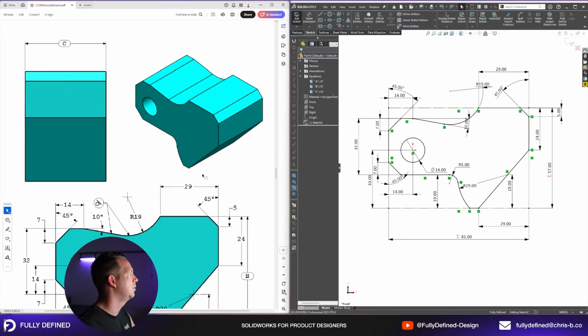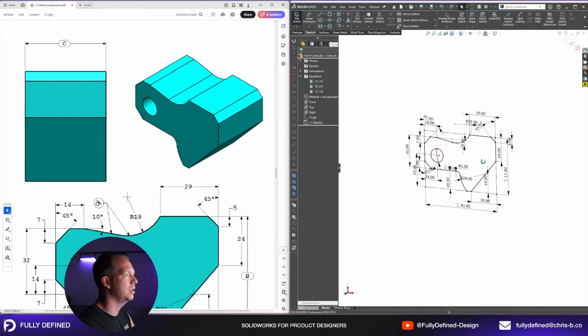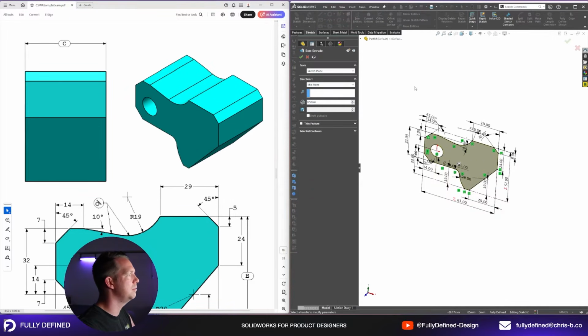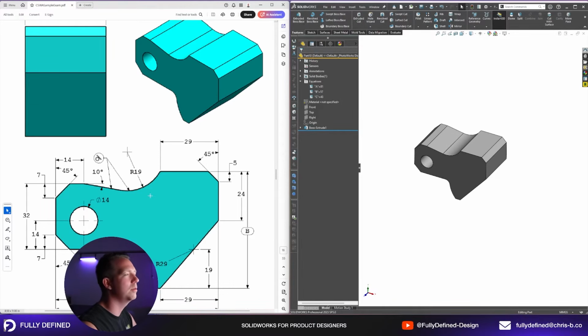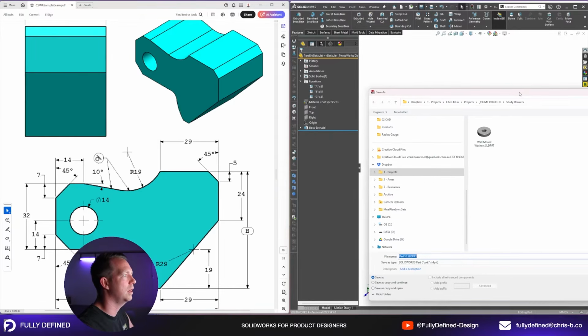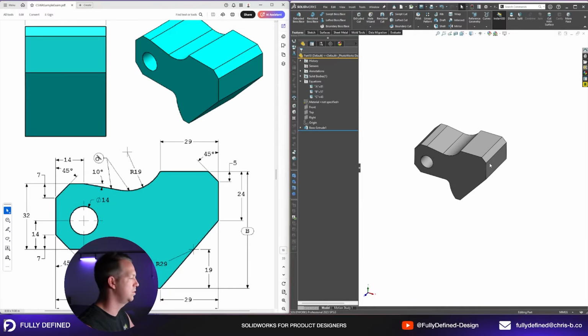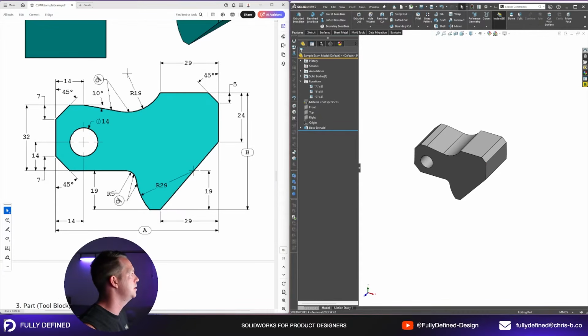Now with that done, we can extrude it, and we want to extrude it by the distance C. Let's extrude it mid-plane, and let's hit for distance 1 equals global variables C. Okay, and that bit is done. So we've completed the model. It's a good idea at this point to save. So hit the save key, find somewhere to save it, and give it a name, just so you don't lose your work. Right, let's continue on.